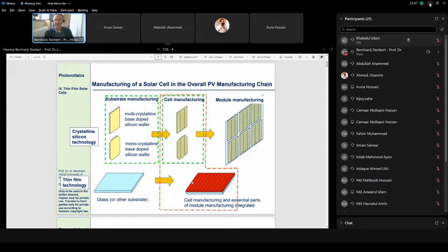Okay, I promised already that I will explain in more detail how this inherent series connection of the cell works. Let me remind you, these are the 3 patterning steps. First one, the back contact is patterned. Then the second one, with a certain offset here, the semiconductor layer is patterned. In this case the example is cadmium telluride, cadmium sulfide, but it would be precisely the same for amorphous silicon or for copper indium gallium diselenide. And the last one, the TCO is patterned again together with the semiconductor layer. And finally, we get this structure.